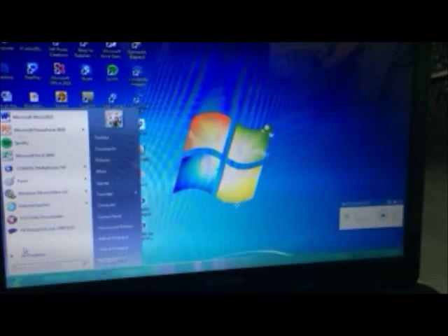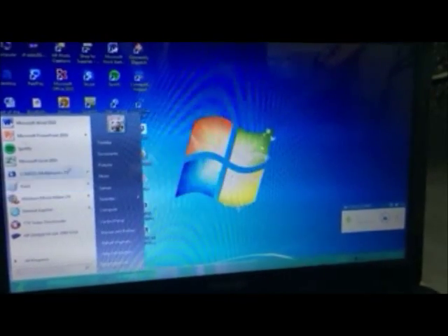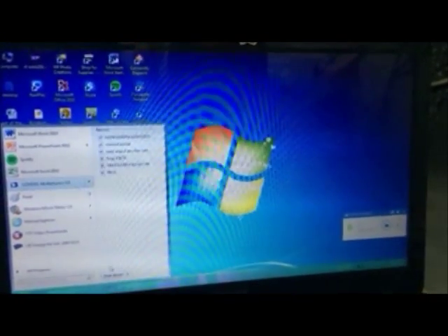Okay, so to do our simulation, we are using COMSOL Multiphysics 5.0. First we add study, stationary, and then we add physics, non-isothermal flow. Here you can see. So then we add geometry.